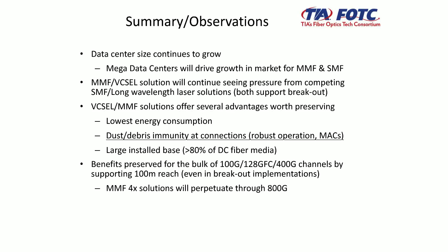As a summary, data center size continues to grow. Mega data centers, hyperscale, drive the need for especially single-mode fiber, extended reach solutions. They want breakout. So the multimode VCSEL solutions are seeing pressure from long wavelength, decosted laser solutions. And now both of these support breakout. The PSM4 solution that I showed you supports breakout.